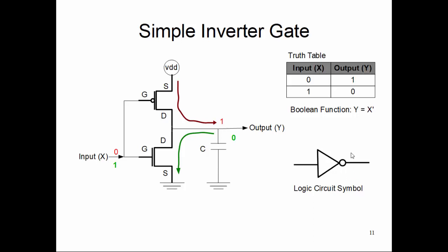So remember, whenever we are drawing a symbol like this in a schematic, underlying this diagram there are physical devices, one PMOS, one NMOS connected in a stack, and the electrical connection is like this. Okay, so inside this one logic gate, we have two transistors connected in a certain configuration, so that it implements the logic function of an inverter.